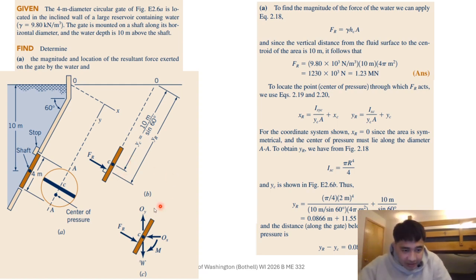Right, and here again, look, here's another key concept. If I were to do a key concept question, this would be pretty good, right? For hydrostatic questions, if the plate is not fully flat and level, the force resultant does not go through the centroid because the pressure is increasing as we go deeper into the water.